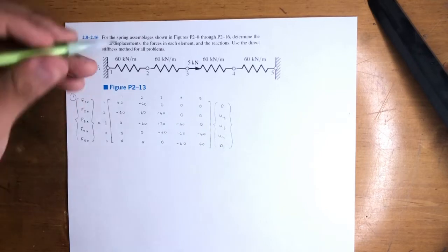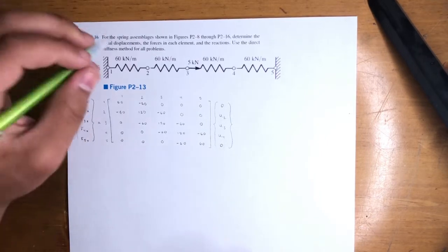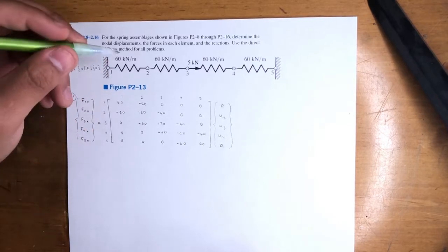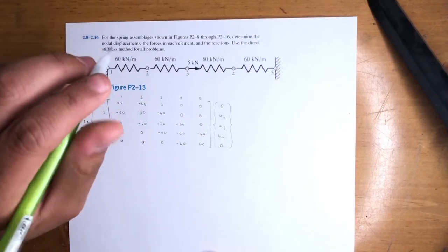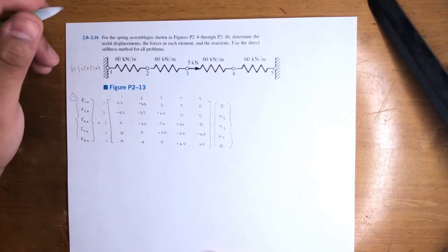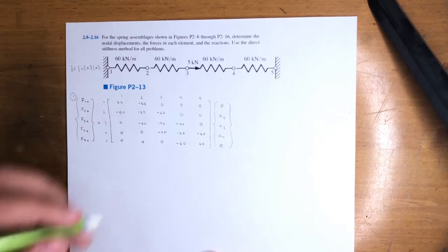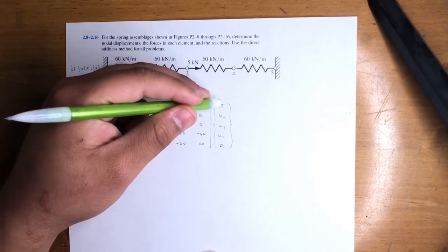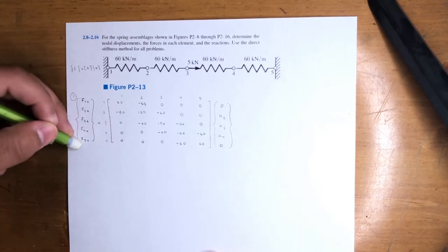What else? Usually, again, if you haven't watched any of the other videos, but you just started watching this one, you know you're doing something right if you either know displacement or force. You would never really know both, and you would never really know none of them. So that's how you know you're doing something right. In this case, we know U1 and U5, so we shouldn't know force 1 and force 5.